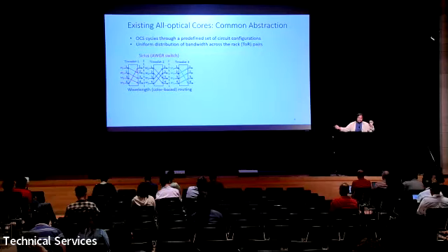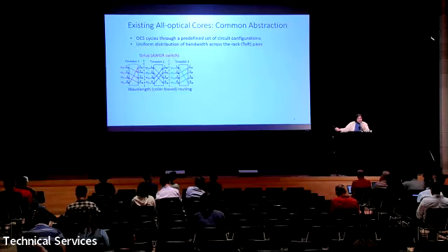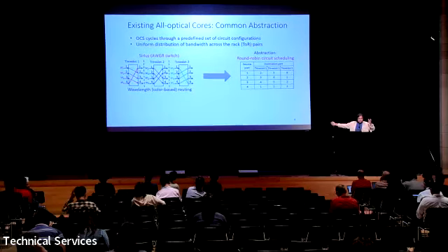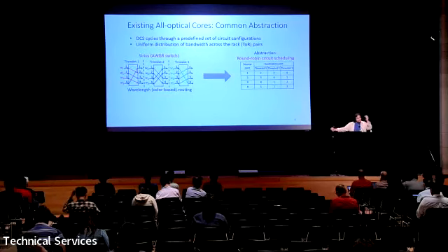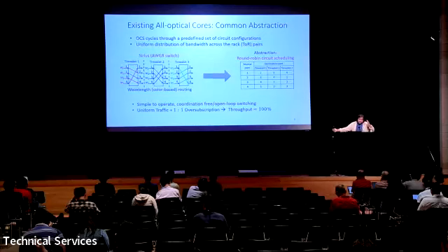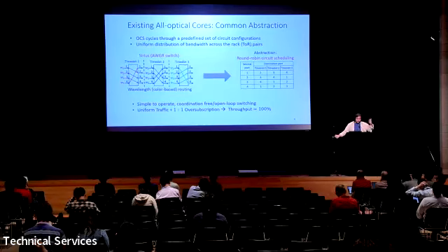So here the idea is if you change the incident color of the light, that will make a certain port-to-port mapping, which is your circuit. So if you have a sequence of colors across time, this will actually convert to a sequence of circuits. And underneath, you will get something like this, where every single ToR is going to get connected with some other ToRs exactly once in a whole cycle. And that thing is perpetually going on, right? To get a reconfigured non-blocking connection. So this kind of architecture is great because you don't need any kind of external control. This can go on forever.